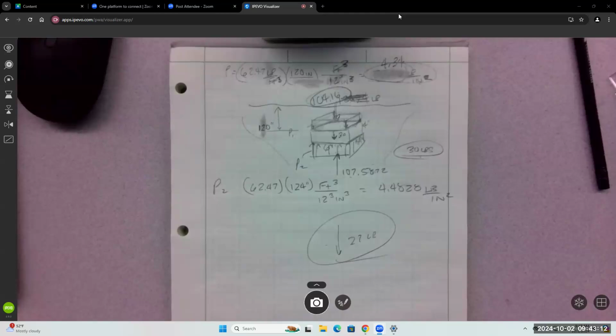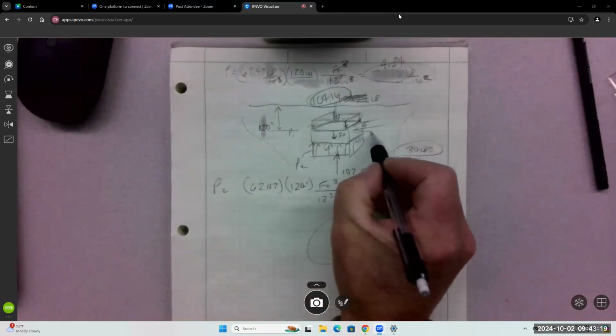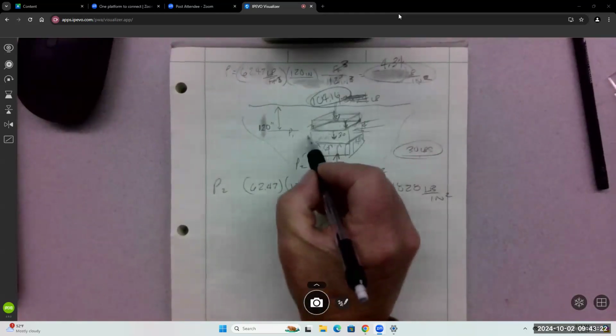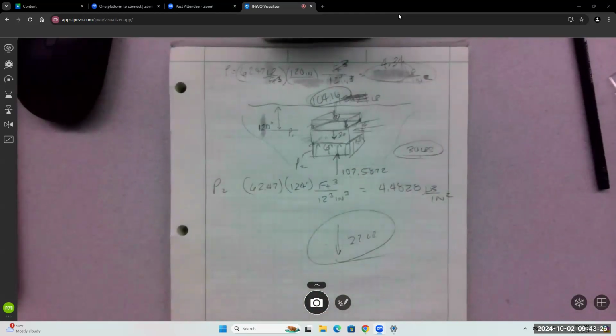One last thing. Why didn't we calculate all these? Don't all these have this side load too? Those are neutral. They're not doing up and down. They're not helping or hurting the float. Now, if you take the object and tilt it on its side, you have a massive problem to figure out whether this thing floats, because you have to do all the sides then. The good news is there's a slightly easier way to do it that we'll learn next time.